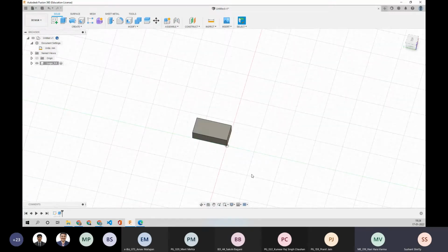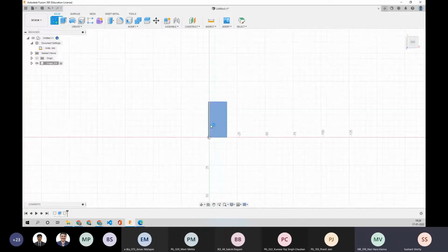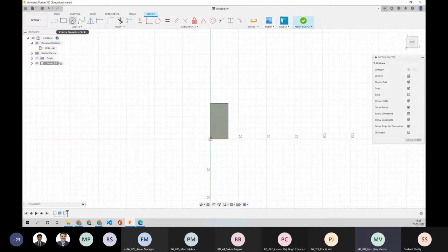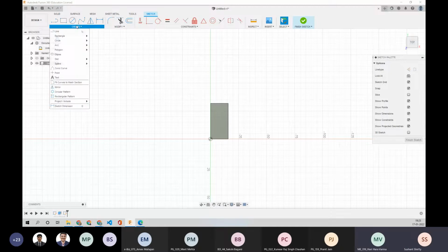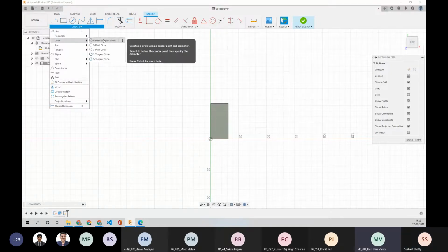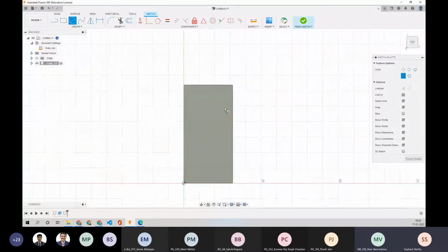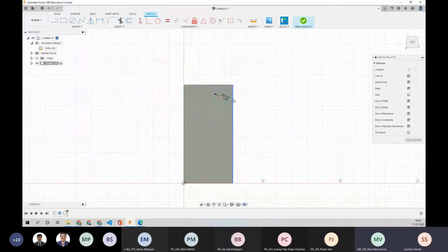Okay, now you want to create those small circles on top which fit onto other pieces. So you'll go to create again, and you'll go to sketch. You will select the surface because it's on top. You'll go to a circle. You can create a direct circle also. This one. Now you can zoom in and you can place your circle somewhere around here. And it's a 5 mm circle. So you say 5 and it sets here.